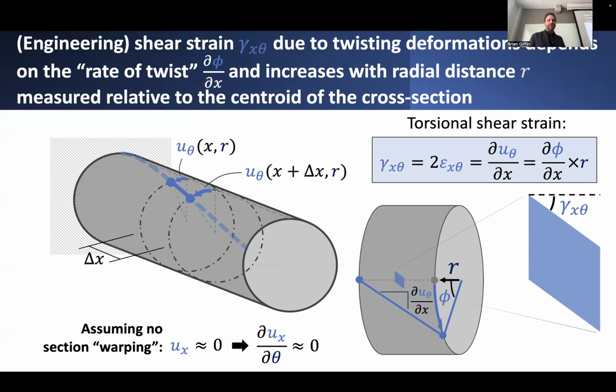And given this description of, you could call it circumferential displacement, we can then also apply our usual kinematic relationships or our strain displacement relationships. And if we assume in the case of torsion that individual plane sections undergo no other deformations apart from these rigid rotations, then it's reasonable to say that the resulting strain that would develop, let's say shear strain under this torsional deformation, we can measure by considering some kind of finite slice of this shaft.